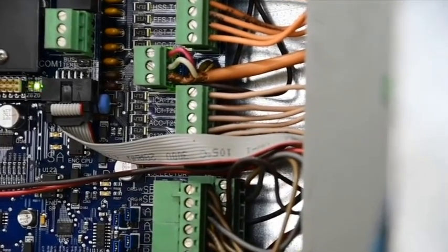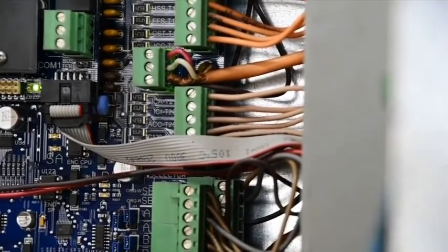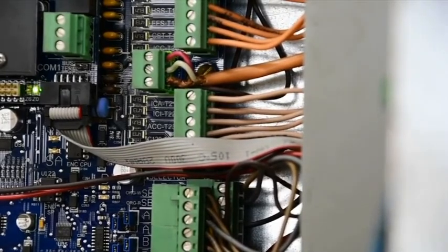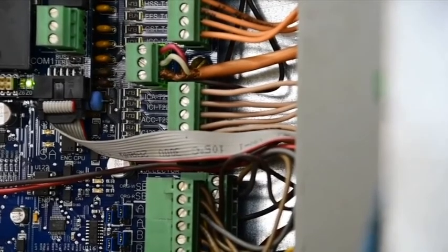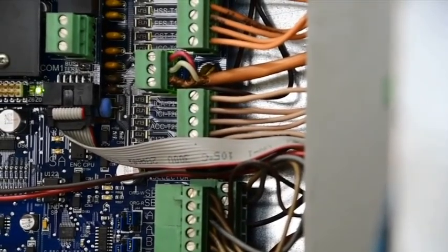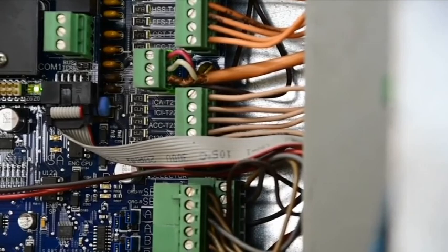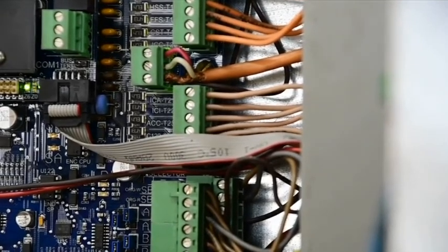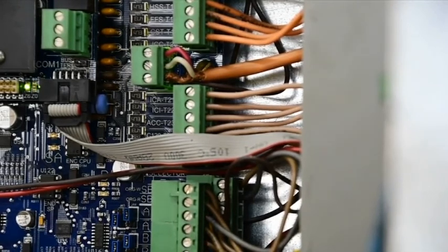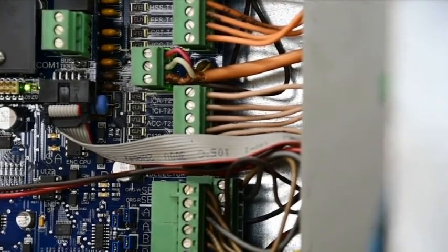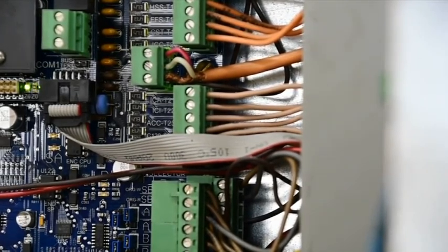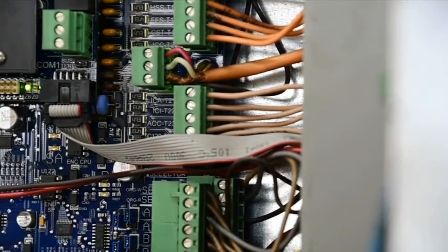Now, for the redundancy, what we do is we have to have at least one input on. We can't have 2, and we can't have 0. There's got to be one and only one of those 5 inputs on at a time. So in order to verify this, we are going to remove the ICA jumper. Now that's in-car automatic. And what that's going to do is, with all the other switches in automatic operation, we're going to remove that wire, which means that none of the inputs are going to be on.